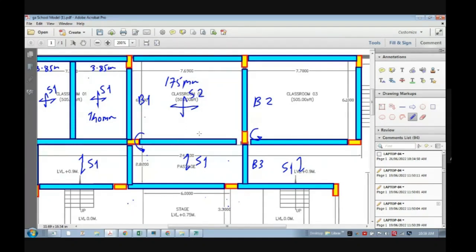Okay. So that's why this looks okay from my point of view, because even though there is a moment, let's say this moment is something like 50 here. यहाँ थोड़े कम होंगे लेकिन फिर भी ज्यादा रहेगा, 40 let's say. So if you design this column on the deeper axis, steel requirement will be less because we have more depth along the direction of the moment. But here we have very less depth, that is 230 width. So I think this may be the better choice.